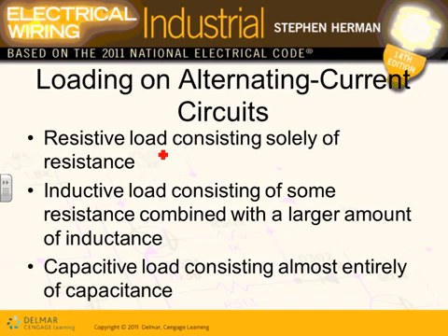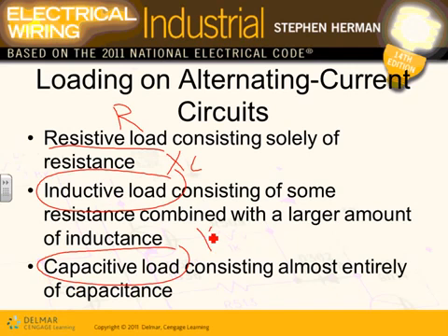When you have a coil in a motor, I have the concept of the resistive load, that's your resistor, my R. Then we also have the inductive load, this is my XL. And there's also the capacitive load, which is my XC. That's part of it when you put a capacitor in the system. So when you connect any electrical load in a power system, this electrical load will have an impedance.